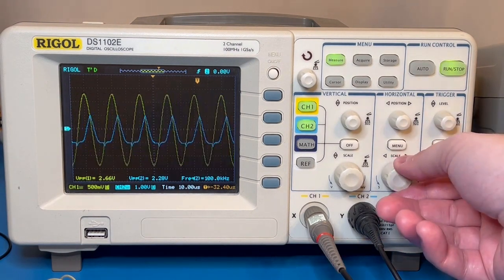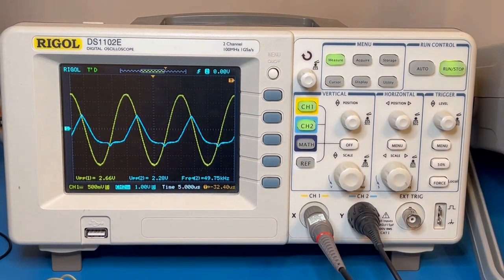And if you go higher in frequency, here's 50 kilohertz, which, if you recall from the small signal analysis, or the small signal test, looked perfectly fine. There was a little bit of a phase shift, but apart from that, it looked really good. Now here at, looks like 2.32 volts of output, the output looks horribly distorted. It's very lopsided. You have almost nothing going on the low side, and it's almost the same voltage level as the input voltage. It's actually a little bit lower peak to peak, though it's so distorted that it's hard to call it proper gain at this point.